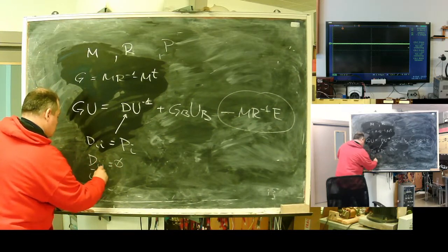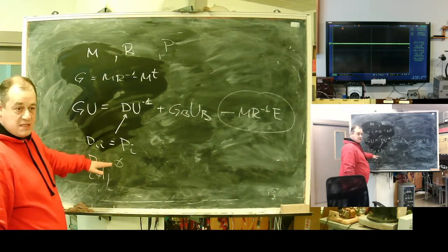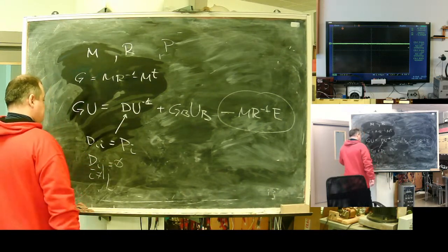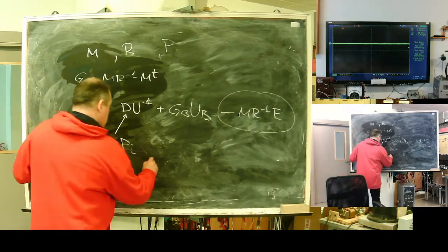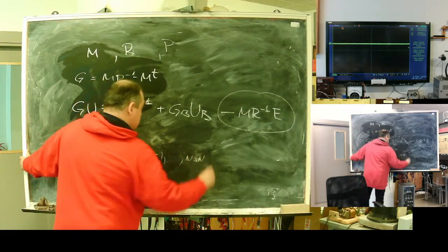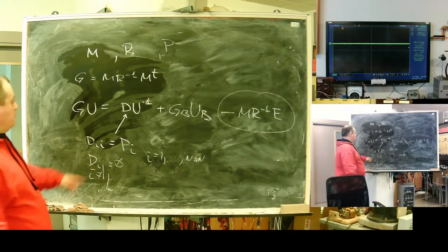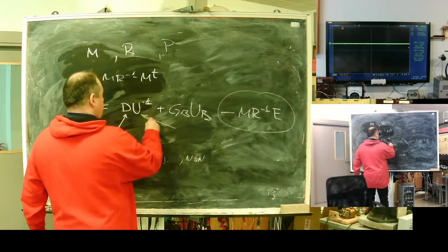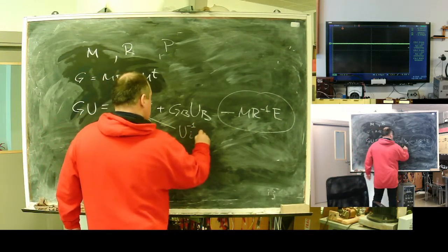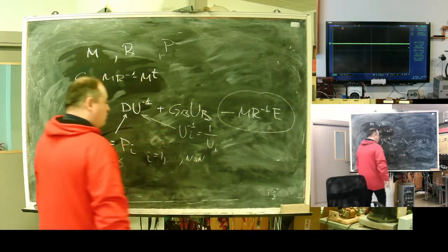Zero excluded, equals the matrix of powers, power by node. I will change I from 1 to the number of nodes. This one, Y inverse I, is again the voltage of node I.